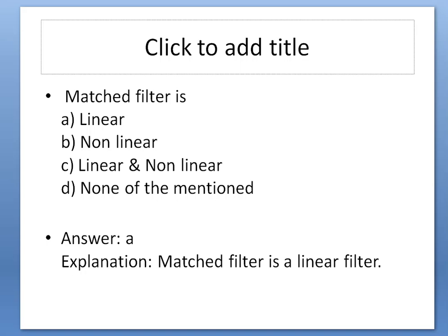Then we estimated the receivable power based upon the EIRP, and the receiving power relations with respect to gain, path loss, and EIRP. Finally we concluded the Friis equation, or range equation, PR is equal to PT GT GR lambda square by 4 pi d whole square.